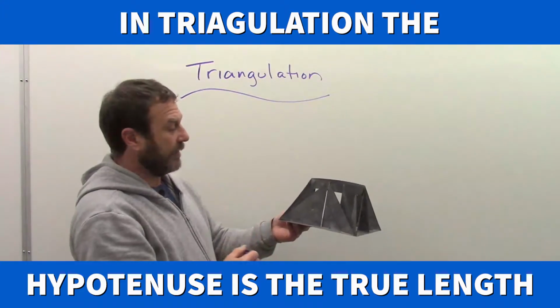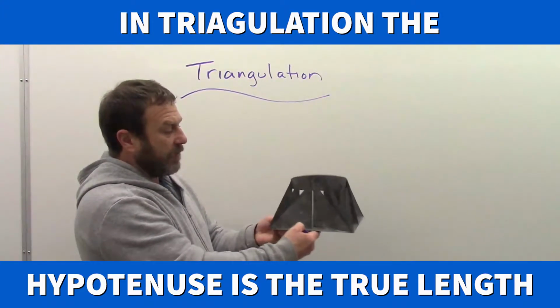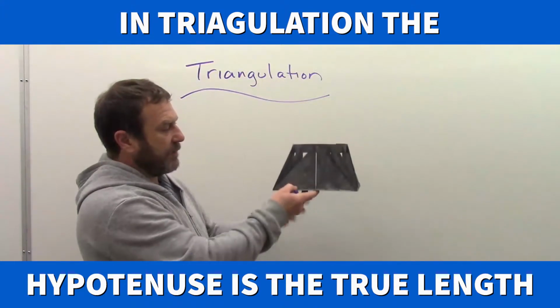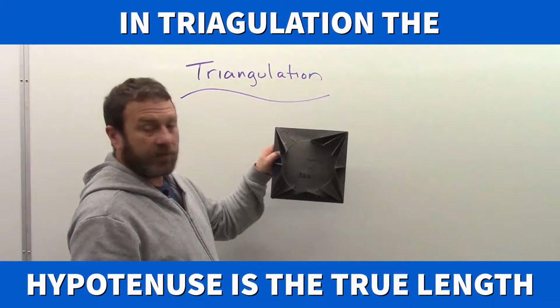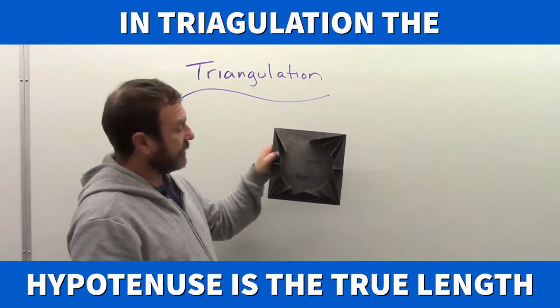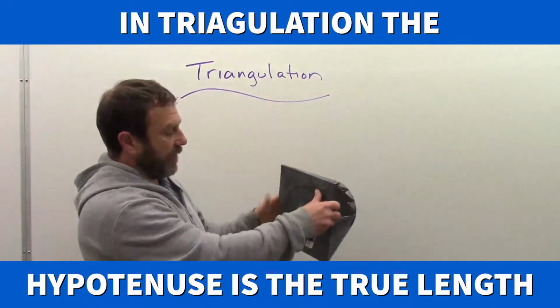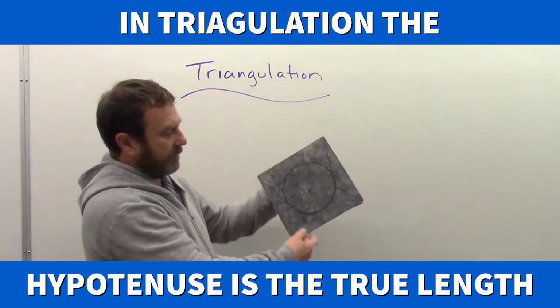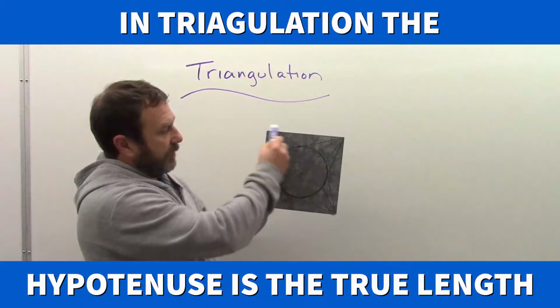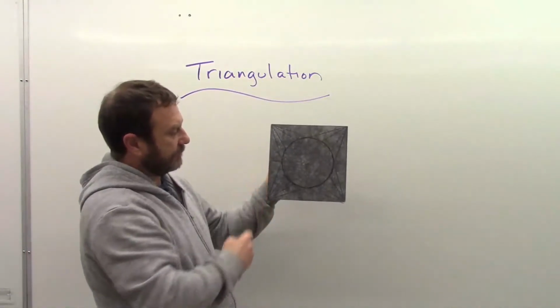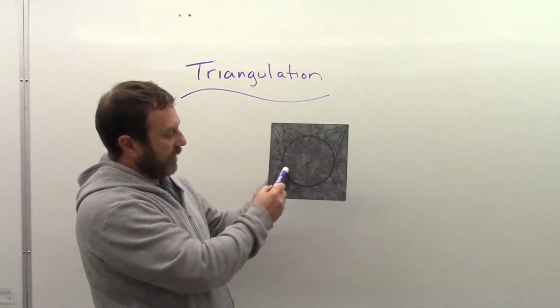That's our element line. Okay, so when we look at this fitting, we would have an elevation view like this, and our plan view would be looking down on it, something like this. I've drawn on the bottom here what our plan view would look like. We have our round shape, and we have obviously our square outside, and we've drawn in our element lines.